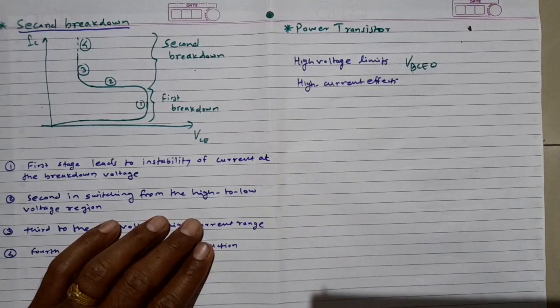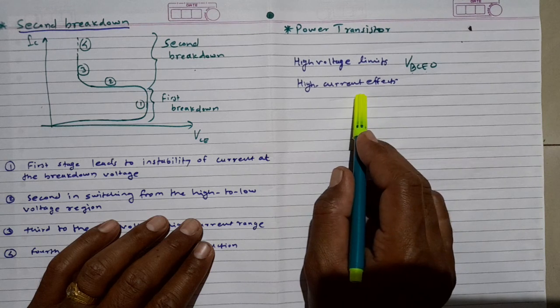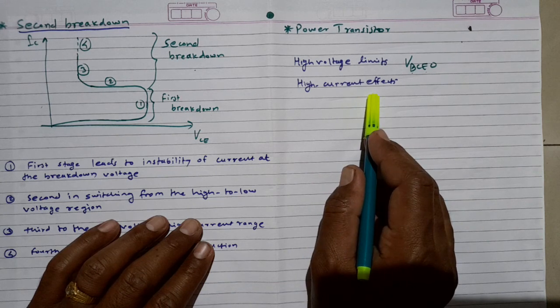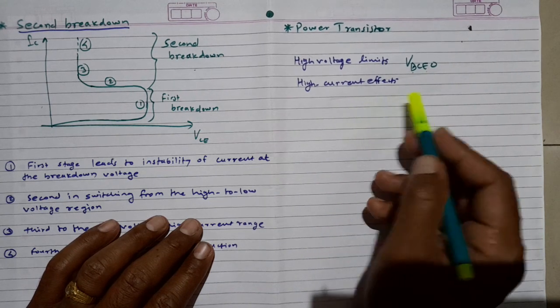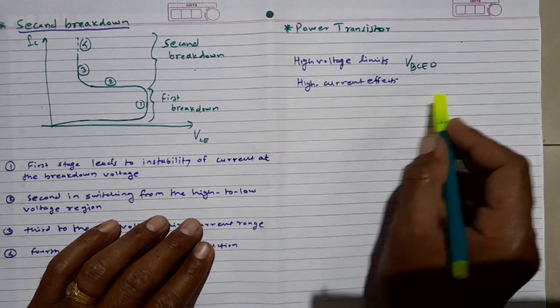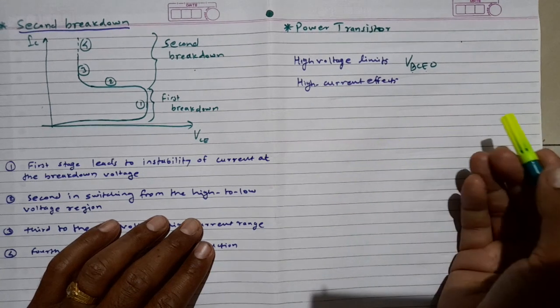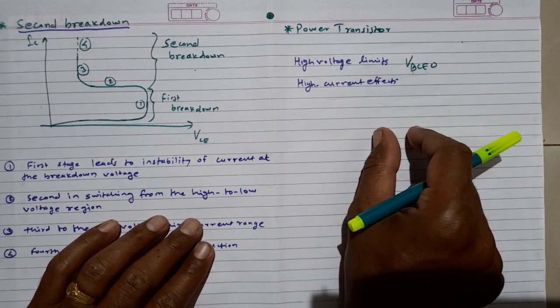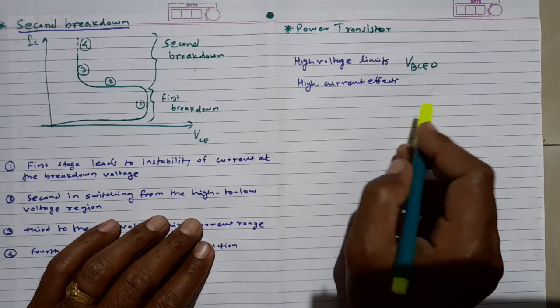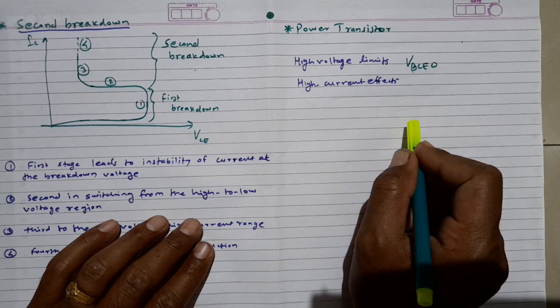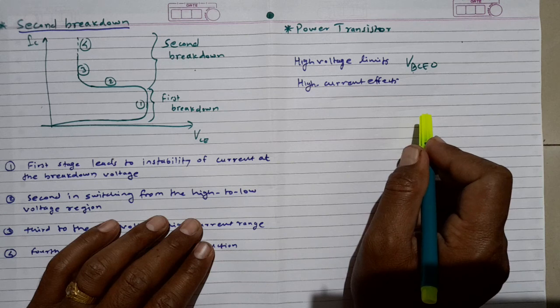What happens when we apply high currents? Under this, there are many undesirable effects observed. Just like base widening due to the Kirk effect, which we have seen before. So the base can be widened, or there is current crowding toward the boundary of the emitter. The current will be crowded at the emitter because of the intrinsic base resistance, which is another factor that affects it.